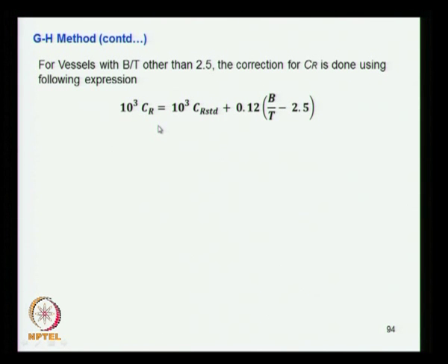Once you have achieved that, you again estimate the frictional resistance using the ITTC formula and get the form factor, and using that you find the total resistance by putting in the other model-ship correlation elements, that is Ca, which you put as 0.0004, then the air resistance and other things, and you can predict the resistance of the ship under design.